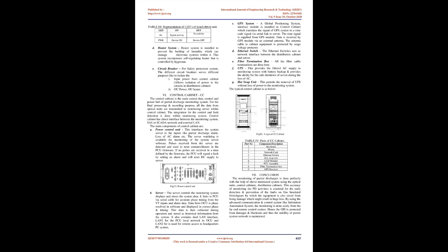The main components of the distribution cabinet are: A. Ethernet switch. The Ethernet switch acts as the interface between the OCU data and the RCC. Ethernet communications between the OCU and RDC can be fiber or copper, depending on system configuration. All connections between RDC and RCC are through fiber. B. Fiber termination box, housing the fiber cable terminations from RCC.